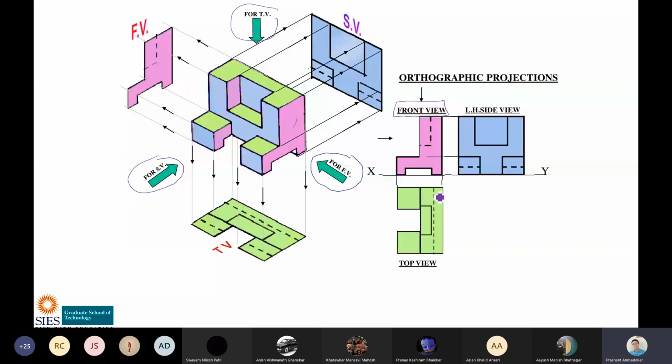And then this dotted line, you can see this dotted line. This was not visible, right? Where is this from, see? Down here there is a slot. This is its dotted line. See, where is it visible from? It is visible from the front view. Project it like this. See, this is the dotted line. It also means that there has to be one line from here also. So this is not drawn. This has to be drawn.